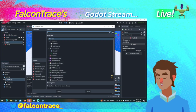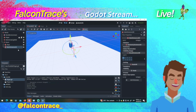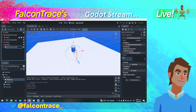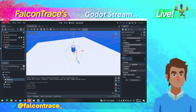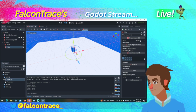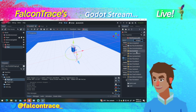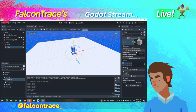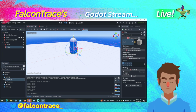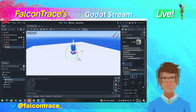We're going to add a new mesh instance. We can double click on the mesh instance over here, and we are going to call it pillar, for example. Over here at mesh, we are going to give it a shape. So let's give it a shape of a box mesh. We can drag it a bit more like this, or using this tool over here, we can put it on the Y.